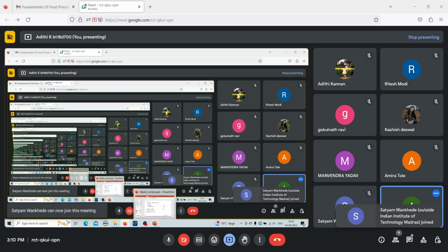So as the name suggests, in this rotational viscometer, you measure the viscosity of a fluid in a container where at least one part is moving or rotating. So you learn different kinds of viscometer. You already know what is a falling ball viscometer that we discussed in the first question and in the previous class. The other kind of viscometer is a rotational viscometer. So rotational viscometer can be of two types. You have coaxial cylinders and you have a cone plate system.